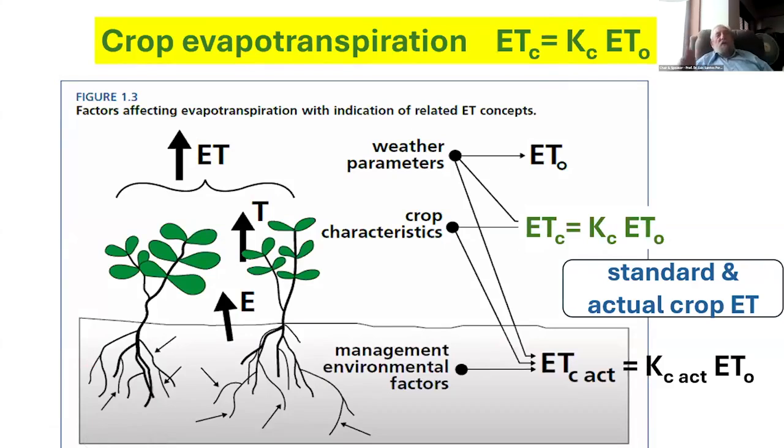Basically, the definition of crop evapotranspiration used by FAO since some 40 years is kept. It means that the crop evapotranspiration ETc is computed as the product of Kc, a crop coefficient, by ETo, the reference evapotranspiration. But we don't just use this definition. We define like that only from the weather parameters the reference evapotranspiration or reference grass evapotranspiration.